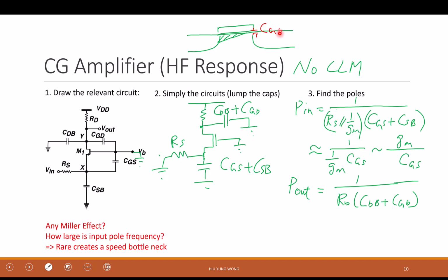No, it's just the process. You are going to have overlap in the diffusion process. Otherwise, you will get disconnected. If it's outside, underlap, then you have a very resistive area. So usually it's a little bit of overlap. So what is the point? Here, usually P out is larger than P in, which is okay.